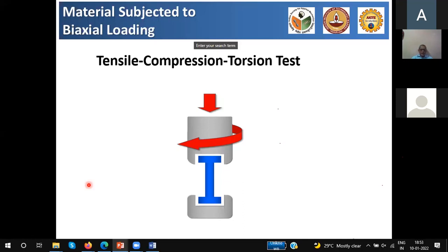So if you are entering into plastic deformation, then there's an anisotropy that is definitely coming into play, and therefore it is required for you to do tests in different directions. If you are still within the elastic limit and you think that the material is perfectly elastic and doesn't undergo any dissipation, you really don't need to do cyclic tests, and you really don't need to even bother about testing things in a multi-axial state of loading.